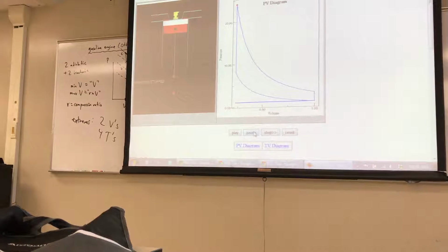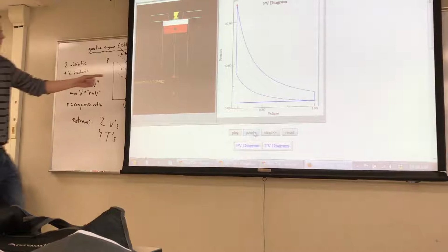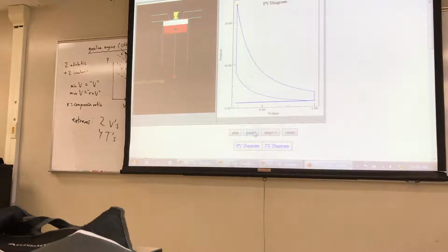So that's called the ignition. We had compressing the gas, which is called the compression stroke. This is called ignition, and now we're ready to make use of the fact that a bunch of gas just exploded in there. It's going to drive the piston down. This is called the power stroke. It's going to push the piston down and cause the crankshaft to turn, so work out of the gas goes into the crankshaft. We had to put work in to compress it, but we get even more work out during the power stroke. That's where your net work comes from.